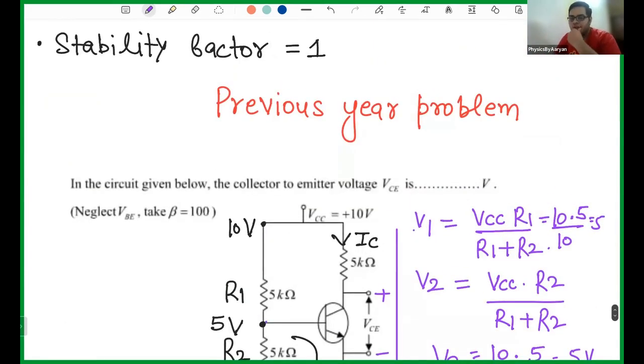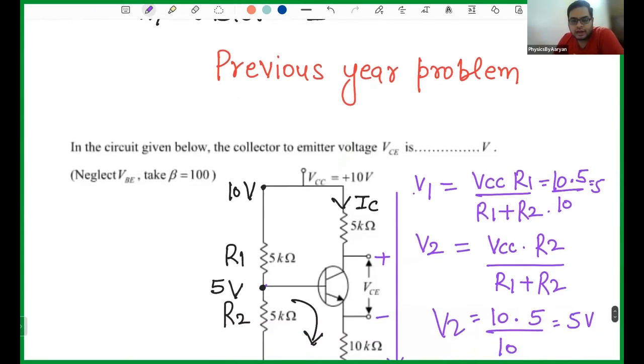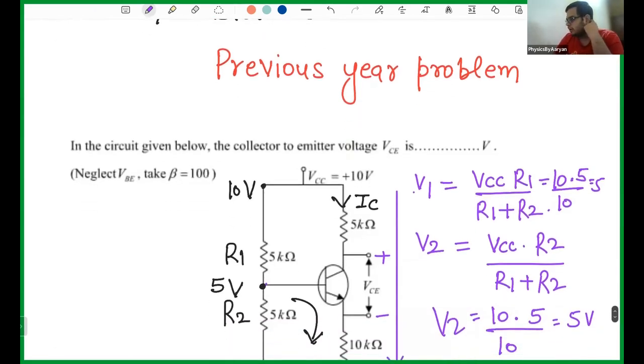voltage division. One thing is very clear from the lecture itself, that there are going to be 4 methods. If you can identify which method is there or which kind of circuit it is, it will help you a lot. Second, there is a very fixed method in which the question is going to come. If you solve all the VK method solved examples, there is nothing which is going to come outside that. Third, you have to be very good in applying Kirchhoff voltage law. There are always going to be 2 loops in which you will apply Kirchhoff voltage law: one will be the left loop and one will be the right.